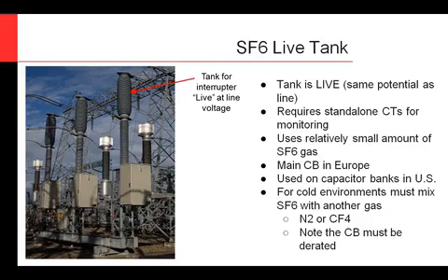Canada, Mexico, they're about 50% live tank, 50% dead tank. One thing I'll mention is these tend to have a lower footprint, because you can see you have a nice small footprint here, but if you need to put CTs, you have to put standalone CTs, so that really takes up the rest of the footprint there and doesn't give you that much of an advantage.